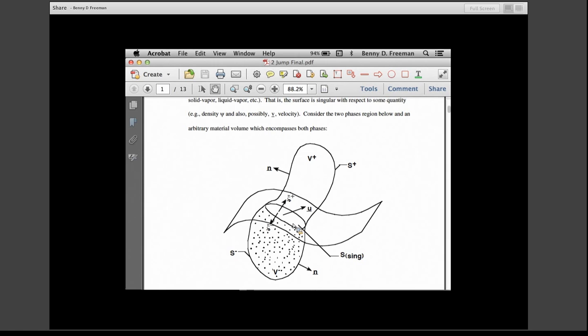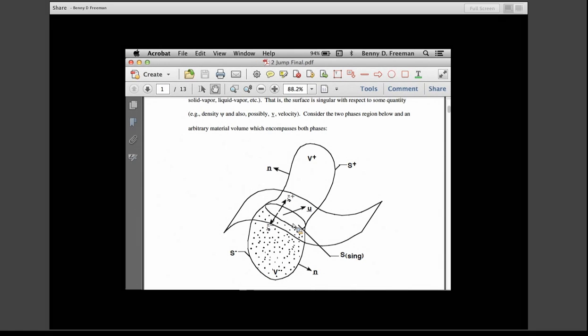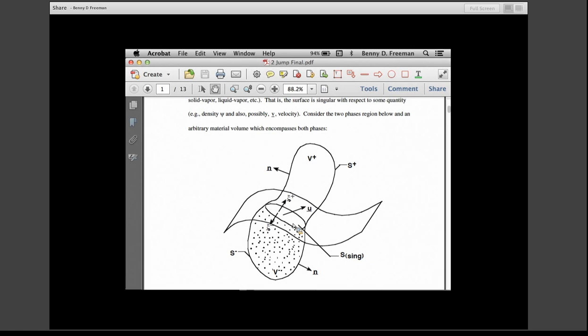And we made a number of assumptions in the Stefan tube problem, one of which is that there was essentially no convective transport of the gas of component B, if you will, the non-evaporating component in that gas phase. And the reason for that is we said that the rate of evaporation was typically so low that the flux of B was essentially negligible relative to that of A.